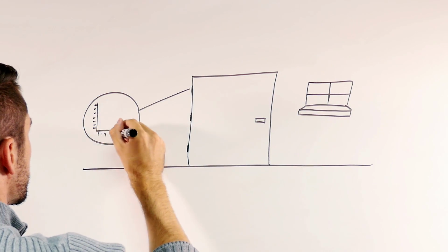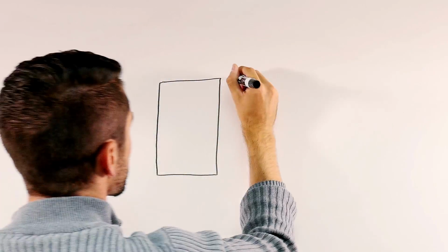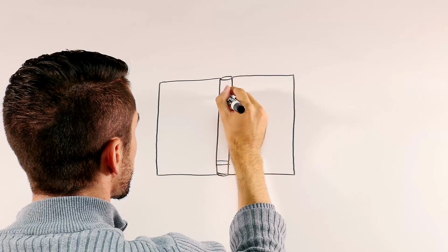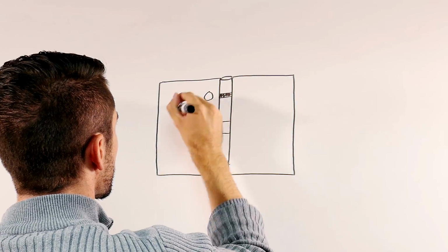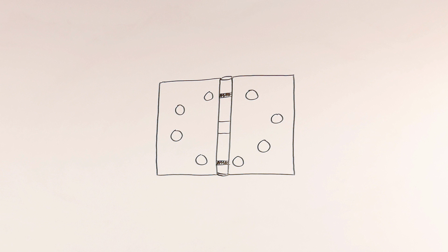Hinge manufacturers, such as Ives, include several helpful charts in their catalogs to help one choose the right hinges for an opening. Conventional hinges, also known as butt hinges, are simply two metal plates, also called leaves, joined by a pin in a knuckled barrel. The pin has a tip that keeps the pin from sliding down and out of the barrel. Many hinges are constructed with bearings in the knuckles to provide for a smooth and consistent operation.